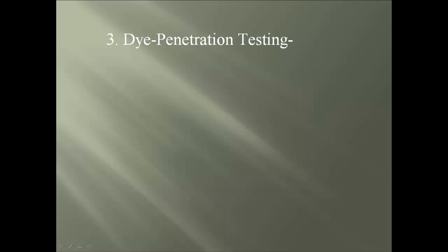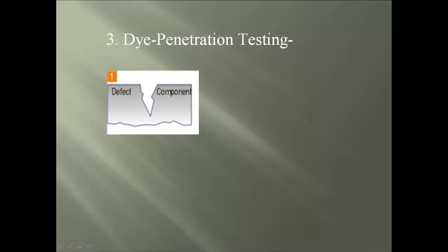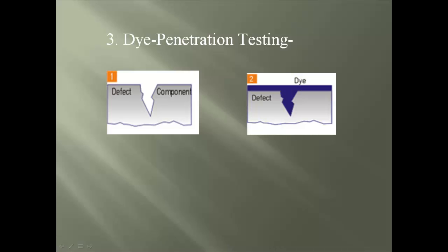The third topic is the dye penetration testing method, also known as PT. The PT method will reveal surface defects and must have a very clean surface prior to moving to the second step of the process, in which a penetrant, usually a liquid, is added to the object, and once allowed to be drawn into the test piece, called dwell time, step number 3 can be performed.